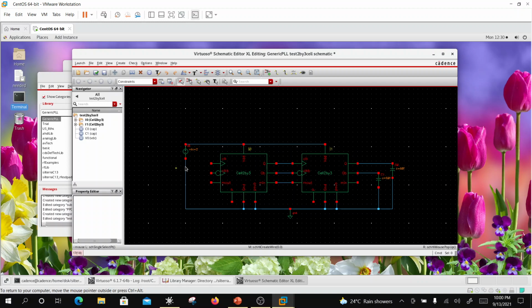And then I have to put clock bar, P0, P1. So this will be P0, that will be P1, and this will be your M in to enable or disable. So when M in is high, then P0, P1 have a meaning. Otherwise, if M in is low, it's always divide by 2, so the net is divided by 4. When M in is high, then P0, P1 will come into picture, right? So let's put here clock bar, and let's be a little tricky here.